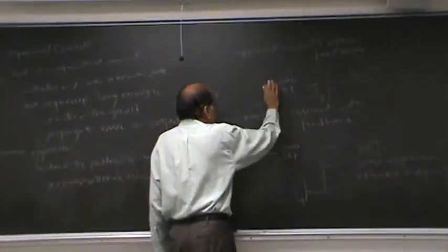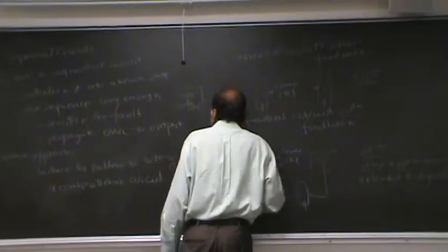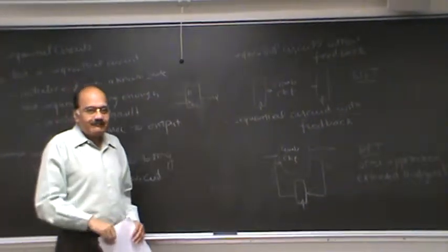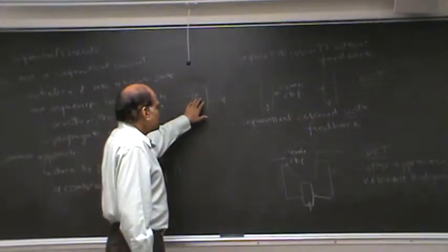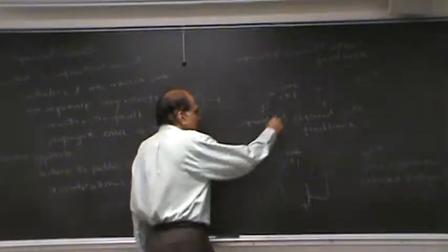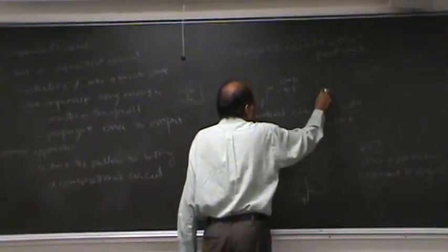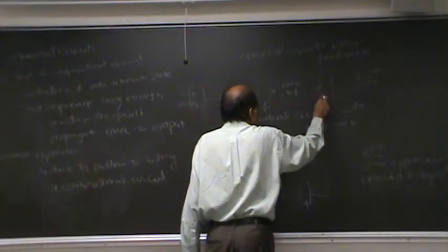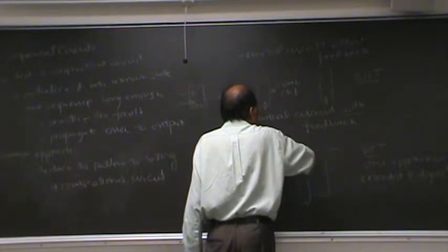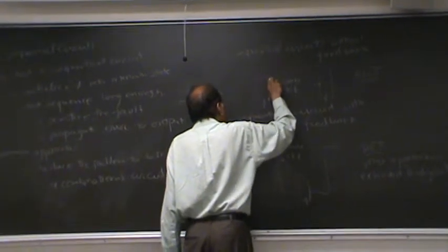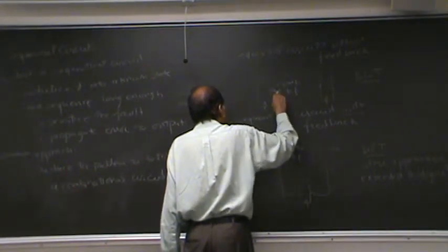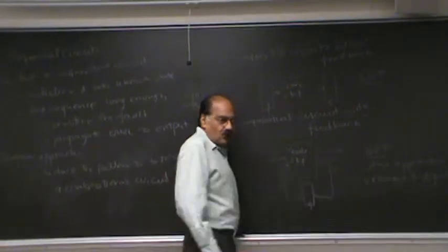So even though you are considering only faults in the combinational logic, you will implicitly consider faults in the storage elements. So, faults at the inputs of these elements can be considered as faults in the output of this combinational block. Faults at the output of this can be considered to be faults in the inputs of this combinational block.